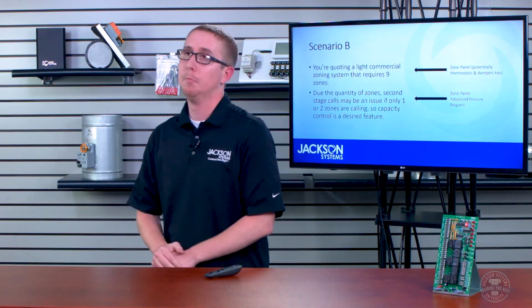All right, and then someone asked, can we use Wi-Fi thermostats that don't have a common? The answer is no. The reason is that the zone panels simply do not respond to non-battery powered thermostats without a common. The components tend to struggle to accept those inputs because they're not seeing the true 24 to 27 volts that they want to see.